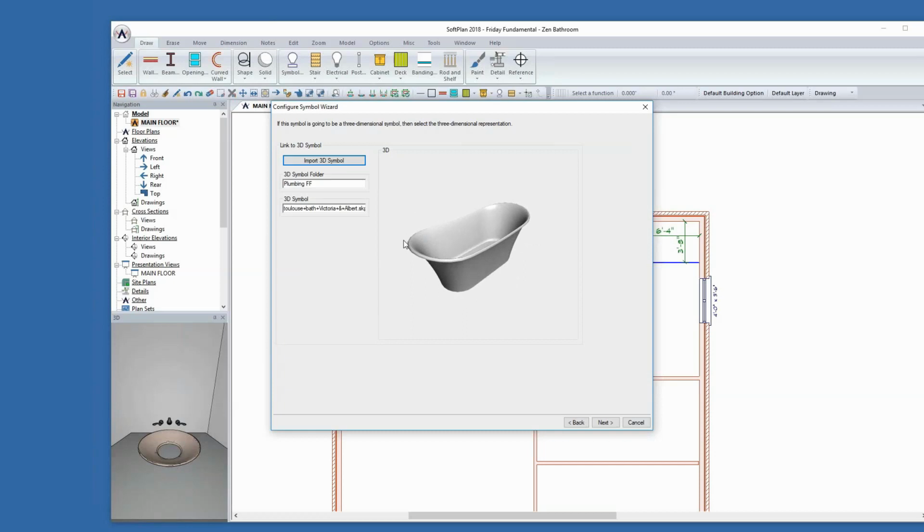I'm going to give you a heads up on this. Some of the manufacturers, as you begin to import them, their files are going to be very, very large. I have in the past imported Wolf symbols, for example. Now, Wolf symbols, for all intents and purposes, they're into selling the detail of their actual specific product. And so their symbol could have 16, 20, 30,000 text or surfaces on it. So just understand that as you begin to bring symbols in, it may cause a slowdown as you begin to use those on your 3D models, etc.